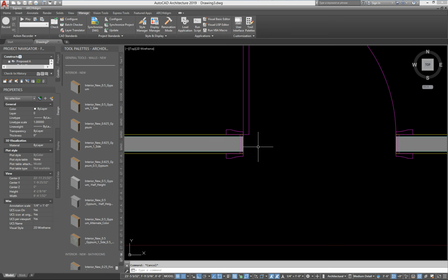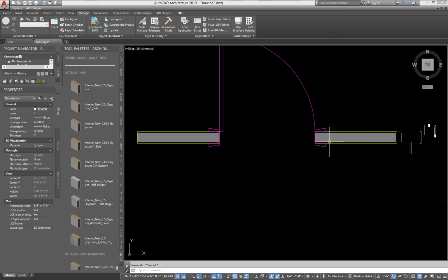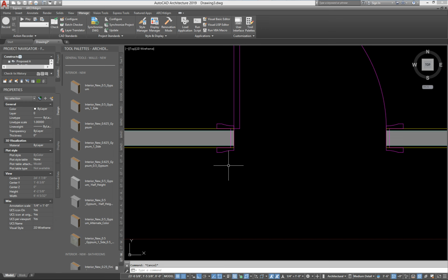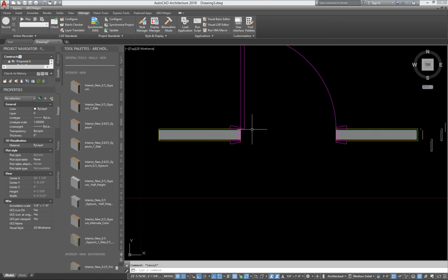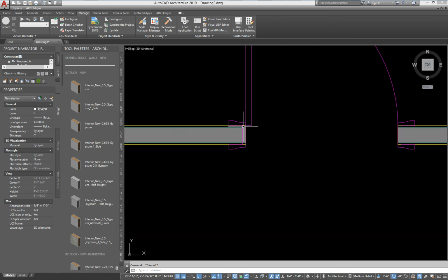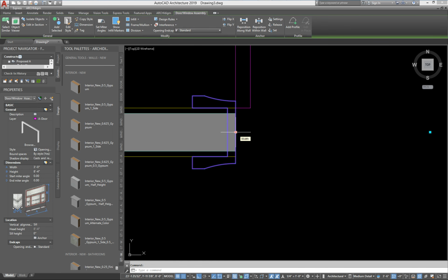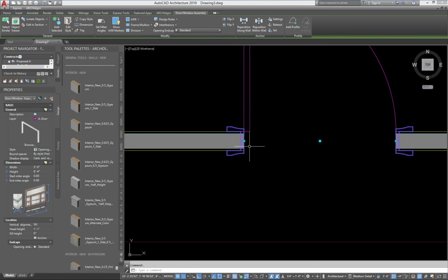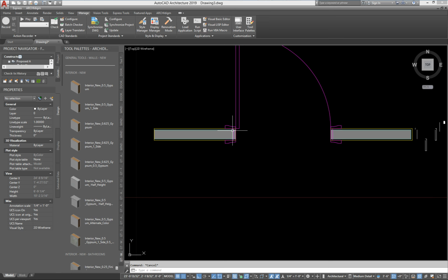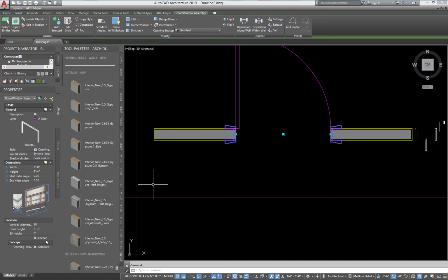So if you insert our custom DWAs into your own wall styles and you see something like this occur, it's because you need a unique opening end cap to make that 3/4 of an inch back spacing off of the wall. Because those DWAs just read to essentially the outside edge. They don't have outside and inside. So we tricked it into doing that graphically, and then we made a custom end cap for it. And that custom end cap is just set in the wall style.